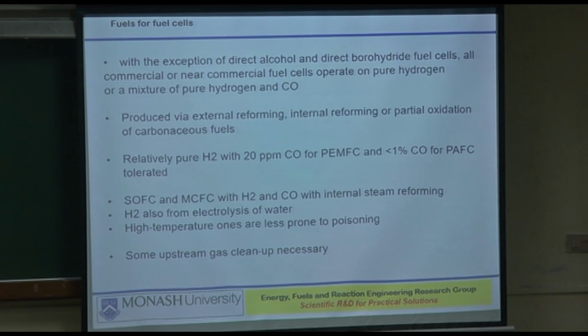Third bullet point: relatively pure hydrogen is required, but up to 20 ppm CO for PEM, and less than 1% CO for phosphoric acid fuel cells is tolerated. So it's still a very low level of CO that we are talking about. That's why I say that some upstream gas cleanup may be necessary.